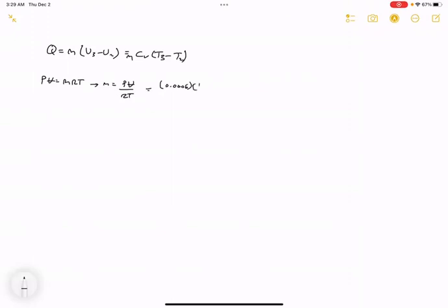Pressure at state 1 is 100 kilopascals. R for air is 0.287 kilojoules per kilogram Kelvin. And the temperature, again given in the problem, is 305. All these values are given either in the problem or from the tables. If you calculate this, you'll get a mass of 6.85 times 10 to the negative 4 kilograms.